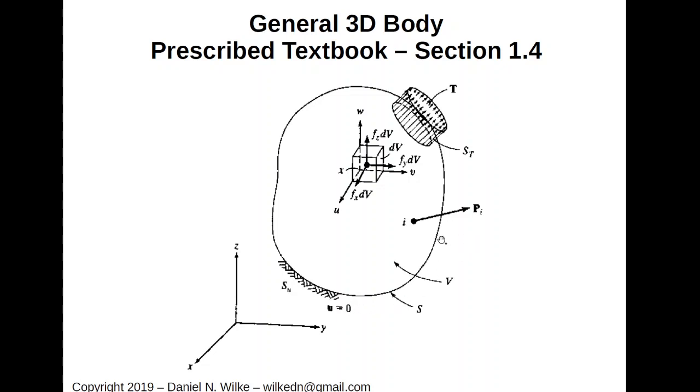Okay, we also sit with possible point loads we could apply to the surface of the structure. We sit with surface tractions we could apply to the structure. These P's represent normal loads in newtons, and we'll see a bit later exactly what the surface tractions are and what they relate to. But these surface tractions are really important, a way for us to see the distributed loading that we have. Surface tractions really are newtons per area. So similarly, it's Pascal units. It's similar units to stress, but it is saying we're applying a load over a certain area. And if I integrate over the area, I would get the resultant force that acts there.